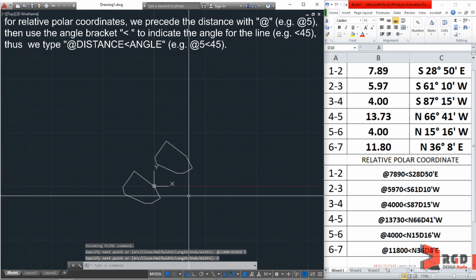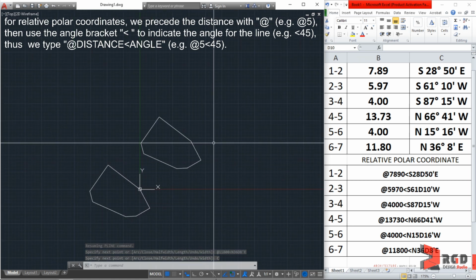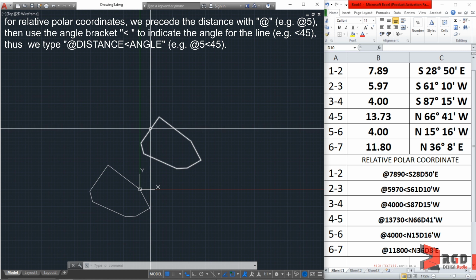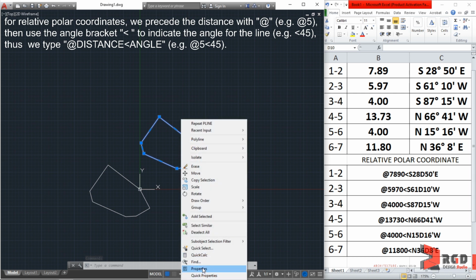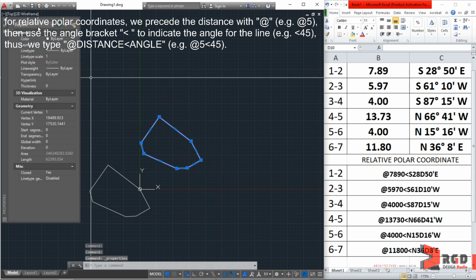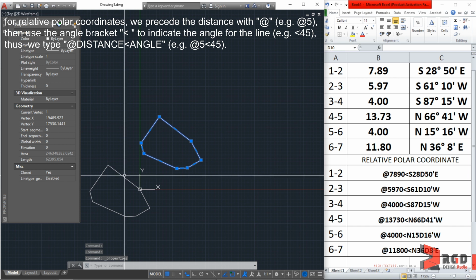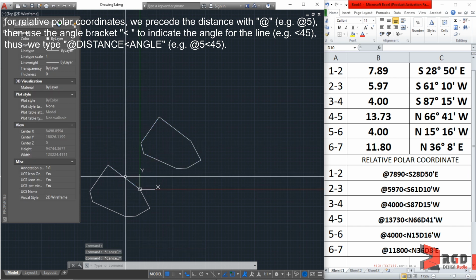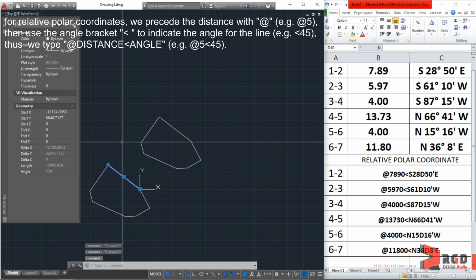Now once I hover my cursor over the lot plan created with the polyline, it could select all of the geometries already. So it's just a single entity. So let's go to the properties. So right click, properties, it's a polyline. But when we click on this initial created, escape first, and then click on this, it's just a line.